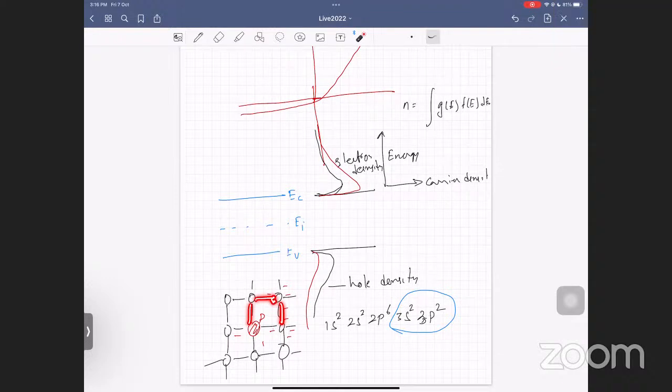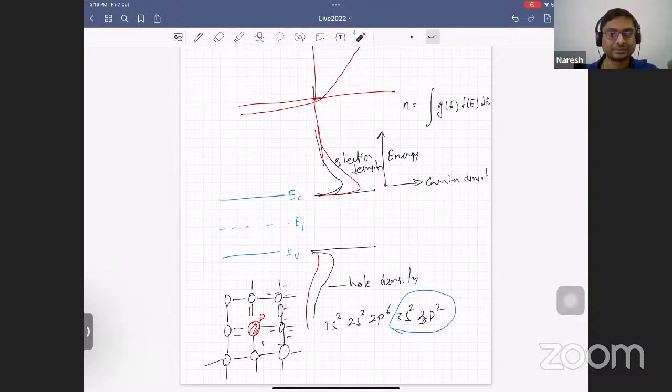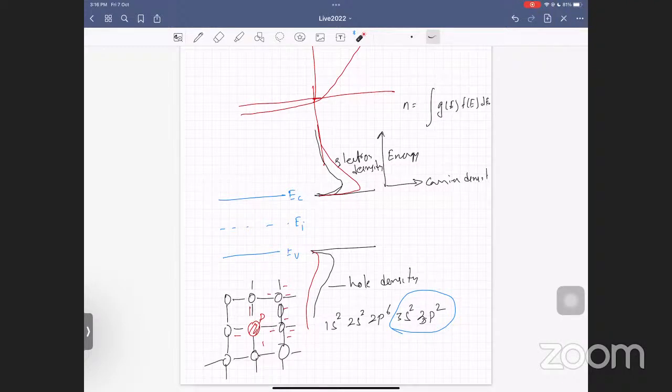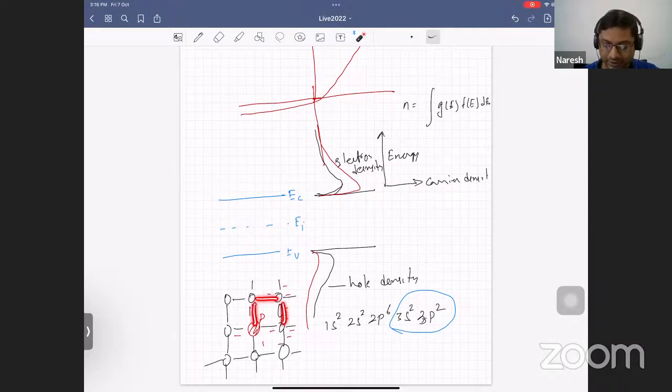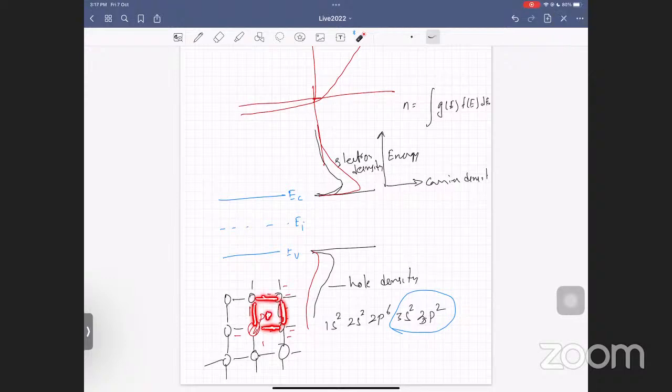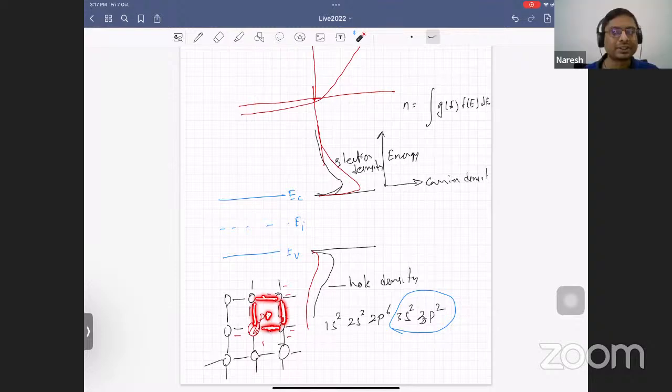Unbounded means conduction band. A free electron is in the conduction band. Whereas if you talk of an electron which is part of the bond like this, there are 2 atoms, right? 2 electrons in between each atom, right? That's what forms a bond. So if it's part of the bond, it cannot move anywhere it wants. For example, the electron cannot be here. Correct? It has to be part of these bonds. When it is part of these bonds, it is said to be in the valence band.